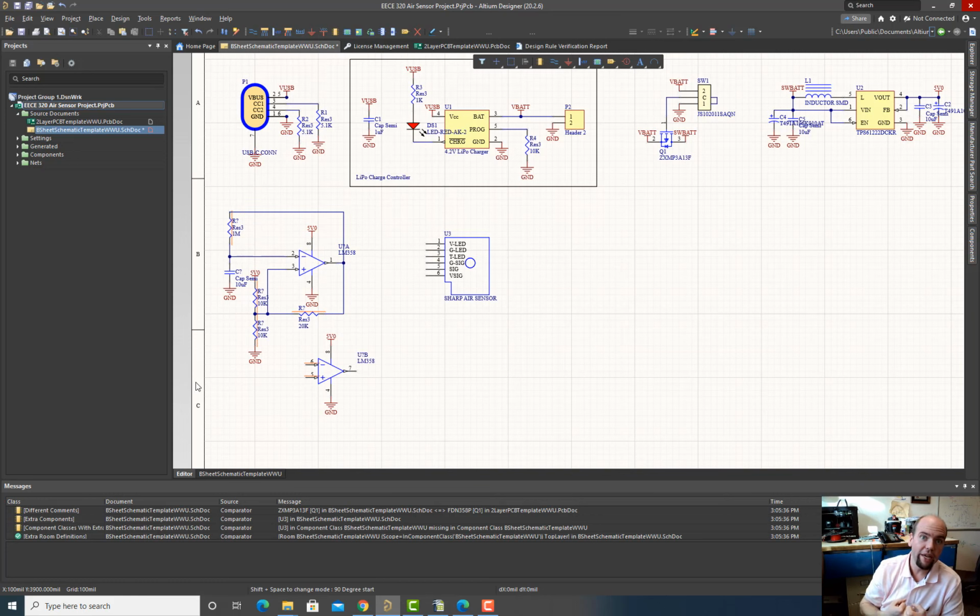Now it has to pull it all the way down to 2 volts before it reaches that threshold, and then it bounces back up. So what we're doing is adding an element of positive feedback that causes this voltage bridge to shift its voltage as the op amp rails in either direction. And that means that when the op amp's polarity switches, it takes time to charge and discharge that capacitor to reach that new threshold value, that new voltage reference value. The time it takes, that RC time constant, determines how quickly this astable multivibrator switches back and forth.